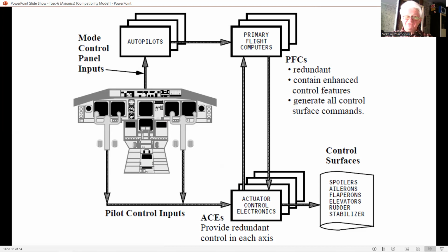The mean time between failures, or MTBF, of a single channel fly-by-wire system is in the region of 3,000 hours. The fly-by-wire system must thus possess redundancy with multiple parallel channels so that it is able to survive at least 2 failures. If these very low failure probability figures are to be met, there is clearly an economic limit to the number of parallel redundant channels.